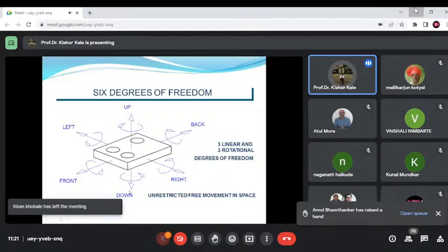Okay. Now how are they functionally defined? Because we have to define these three datums for the verification of tolerances. Okay. So the primary datum is selected to provide functional relationships, accessibility, and repeatability. It ensures the functional relationships. So standardization of size is designed in the manufacturing of a part. Consideration of how parts are oriented to each other is very important.